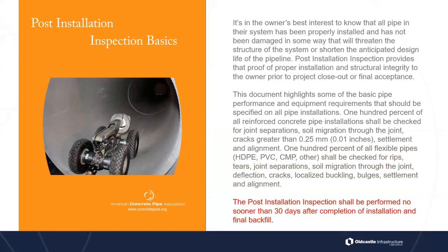Post-installation inspection should be performed no sooner than 30 days after completion of installation and final backfill. Again, because we want to make sure that we've got the time for that pipe to stabilize. So you want to do it 30 days after you install the pipe.